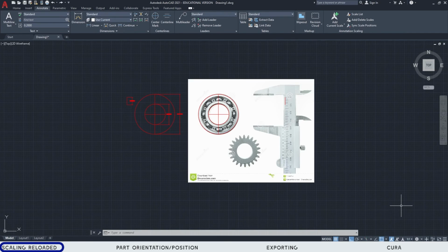Okay, so next is orientation. One of the attributes of a model is its orientation. Therefore, it's important to properly position the model before it's exported out of AutoCAD. In other words, try to set what is up and down before you export the file.